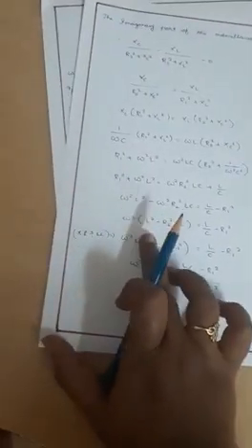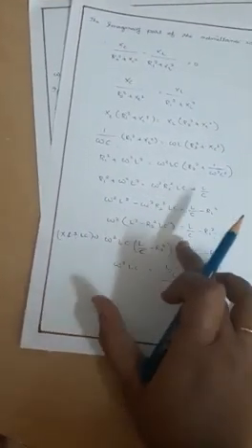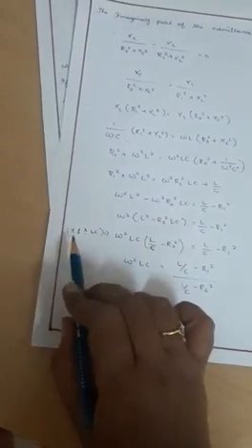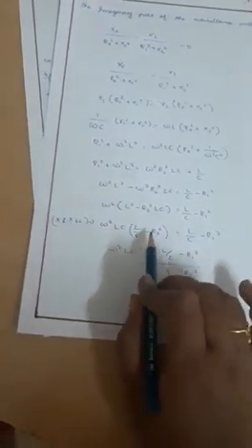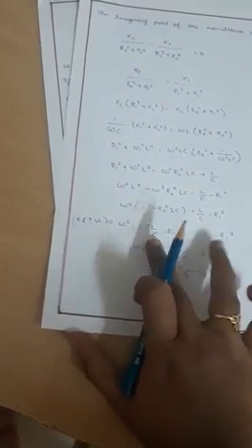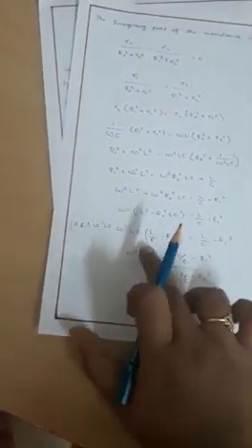By contracting it, omega square into L square minus R2 square LC is equal to L by C minus R1 square. To make the equation simpler, we multiply and divide by LC on the left hand side. So omega square LC into L by C minus R2 square is equal to L by C minus R1 square. We can see the similarity between both sides, L by C minus R2 square and L by C minus R1 square, so this is convenient for us to proceed further.